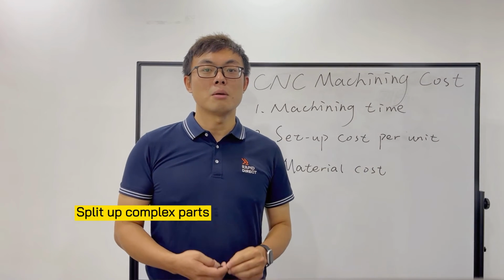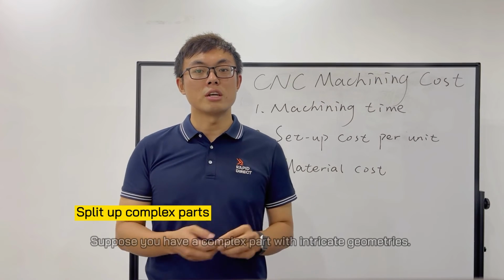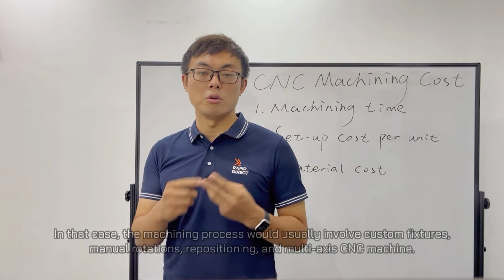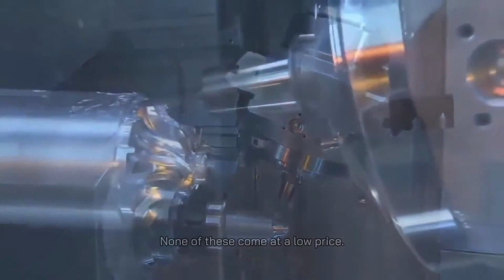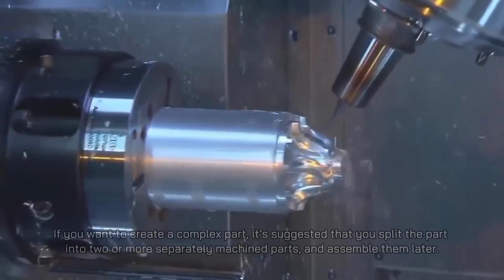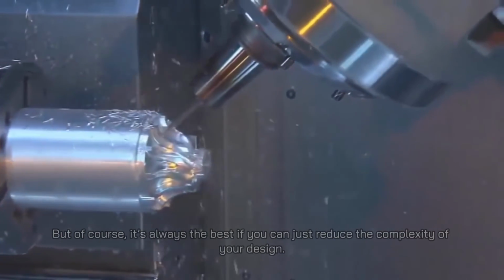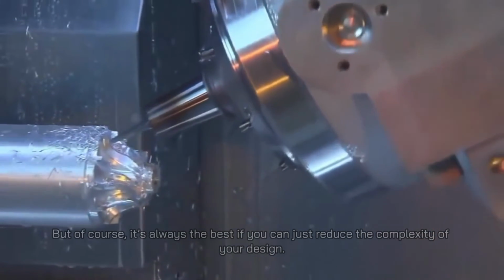Next, split up complex parts. Suppose you have a complex part with intricate geometries. In that case, the machining process would usually involve custom fixtures, manual rotations, repositioning, and multi-axis CNC machines. None of this comes at a low price. If you want to create a complex part, it is suggested that you split the part into 2 or more separately machined parts and assemble them later. But of course, it is always best if you can just reduce the complexity of your design.